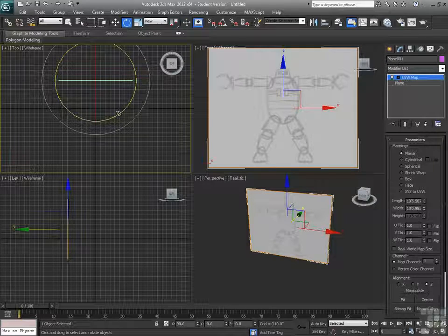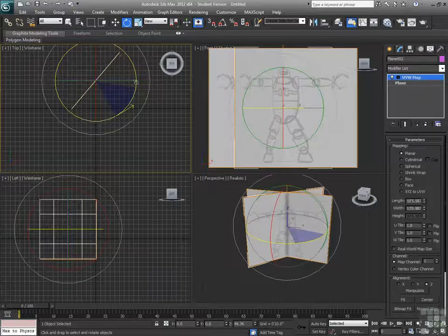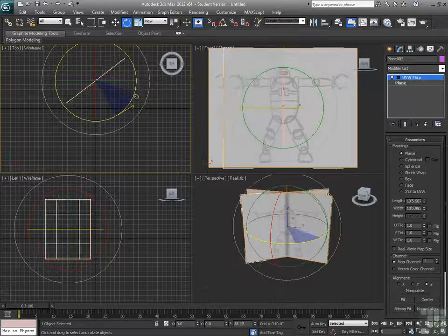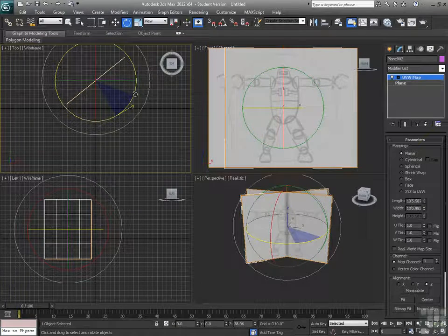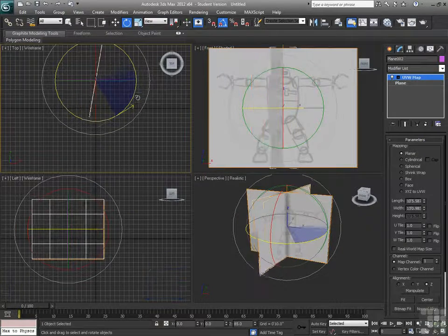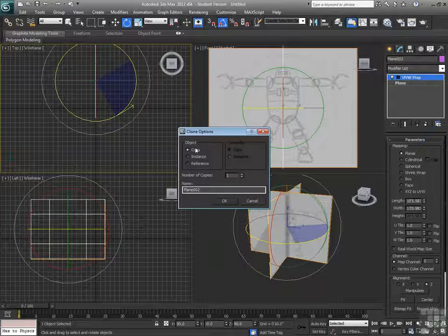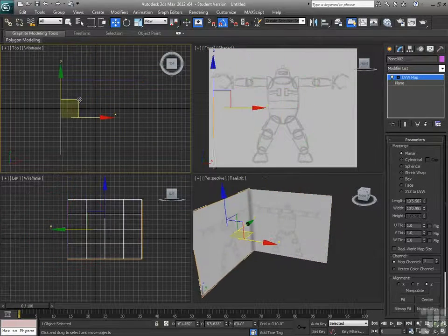So we'll just start by rotating it. If I hold on the Shift key while I rotate, I'll get a copy of my object. But since I'm not rotating with angle snap turned on, while I'm in the middle of the rotation process, I can hit A to toggle on the angle snap. Now that'll allow me to rotate to a perfectly 90-degree angle, and we'll make it as a copy. Then we can grab it, move it out of the way a bit.